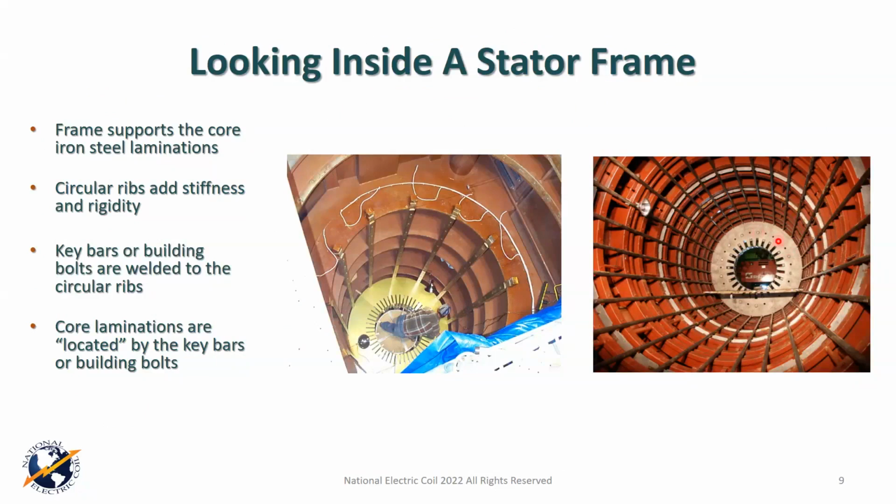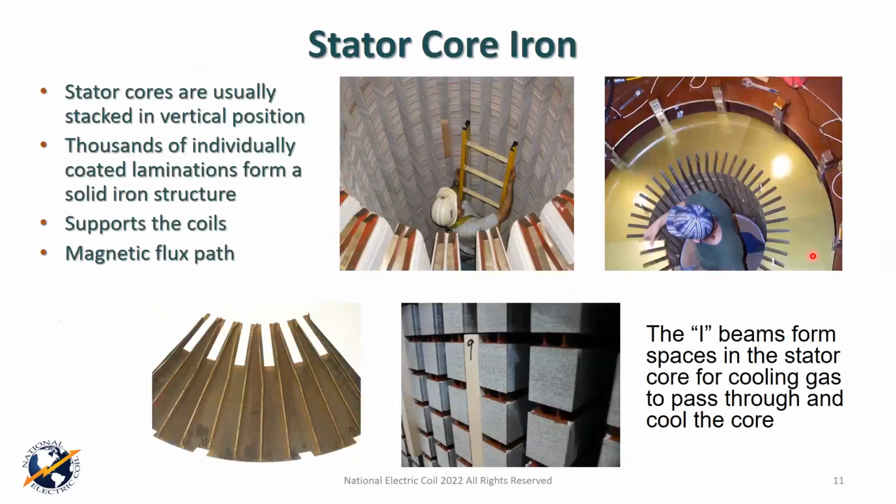It's got the through bolts here, the building bolts in the back. And this GE design only has these key bars that clamp onto the pressure plates and pull it down. And these tended to stay tight more than these. And this has got twice as many bolts in it. I just couldn't process that for the longest time.